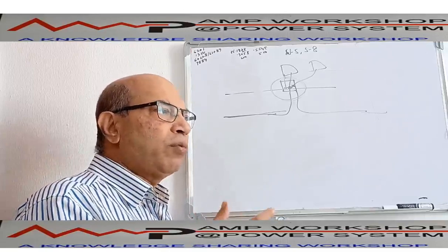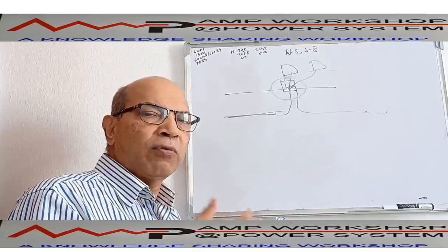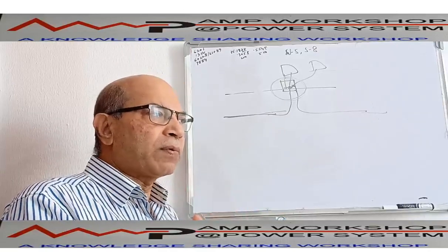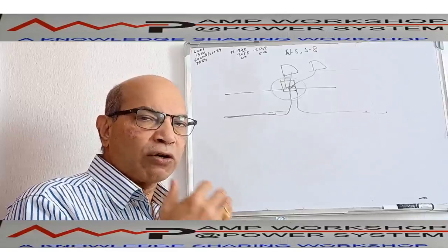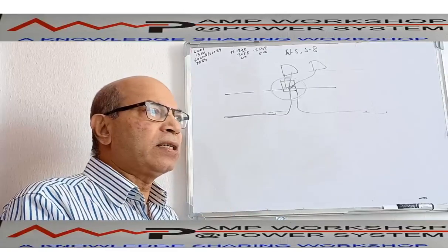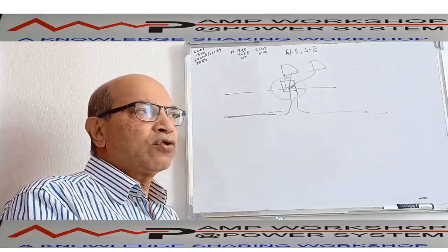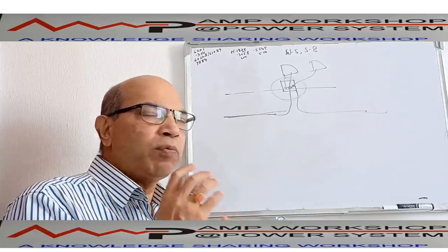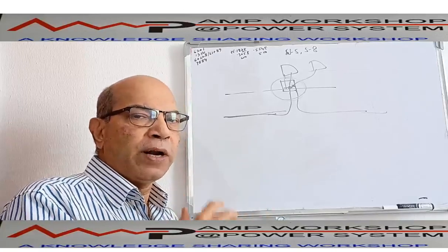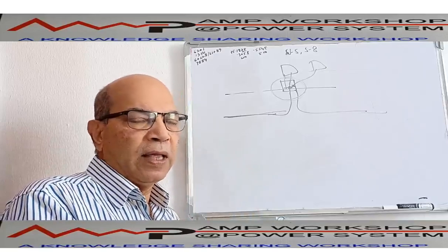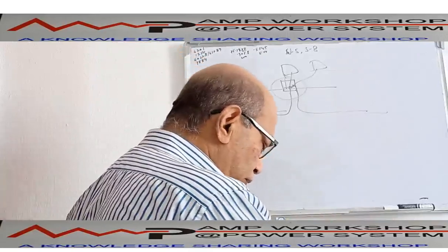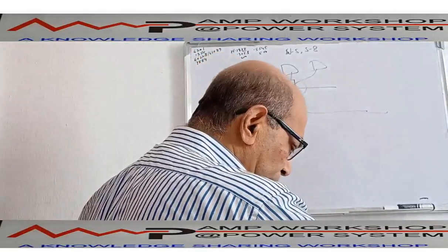Now, there are so many conducting materials, like silver, gold, platinum, copper, aluminum, all are conducting materials. But we have to find a material which is cost-wise optimal and economical, as well as a good conductor with good mechanical strength. So considering all these aspects, mainly two conducting materials are used for the overhead conductor purpose: one is copper, another is aluminum.